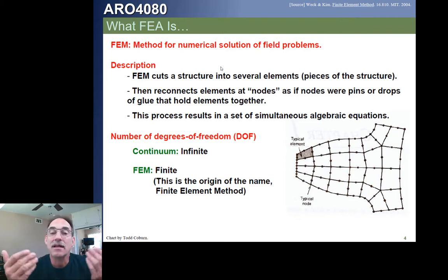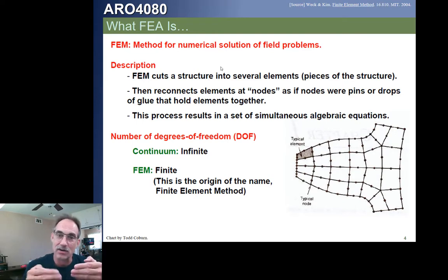We're going to have to tell the machine, the code, the software, what stiffness this has. Is this just an axial member that can carry axial load, or can it carry shear, can it carry bending, those kind of things? All these decisions have to be made. Just drawing a model and letting the computer do its thing is not sufficient for many models.